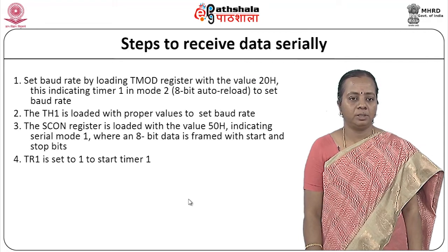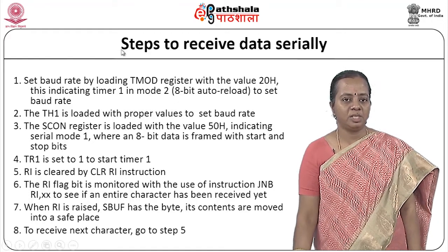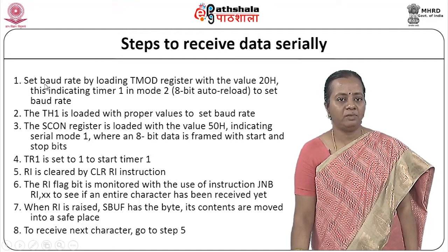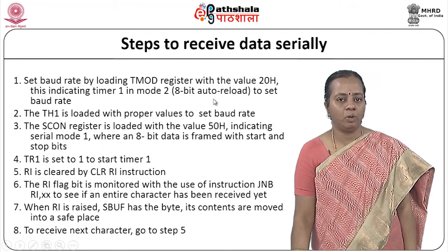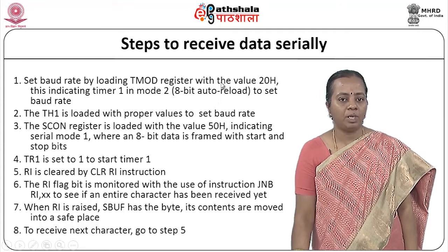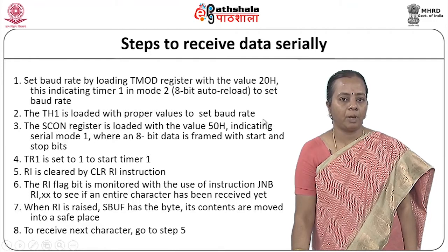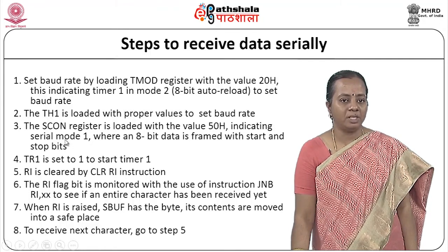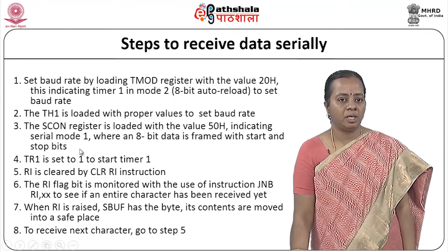The next task is to receive data serially. These are the steps we have to follow. Here you see that we load the baud rate by loading TH1 with the particular value, and timer 1 is set with mode 2. The SCON register is loaded with the value 50, which indicates serial communication mode 1, where 8-bit data is framed with start and stop bits.